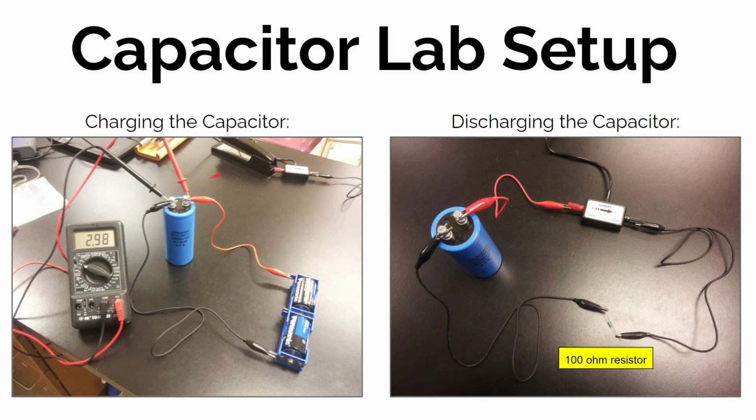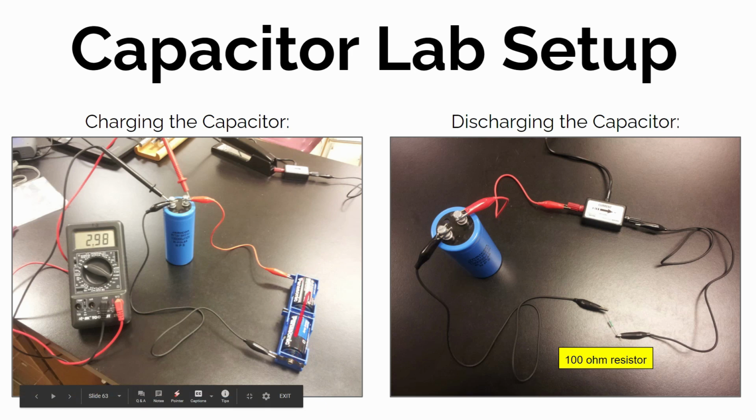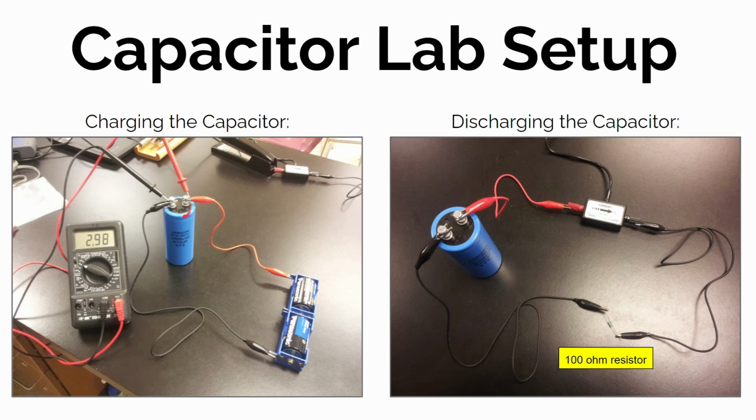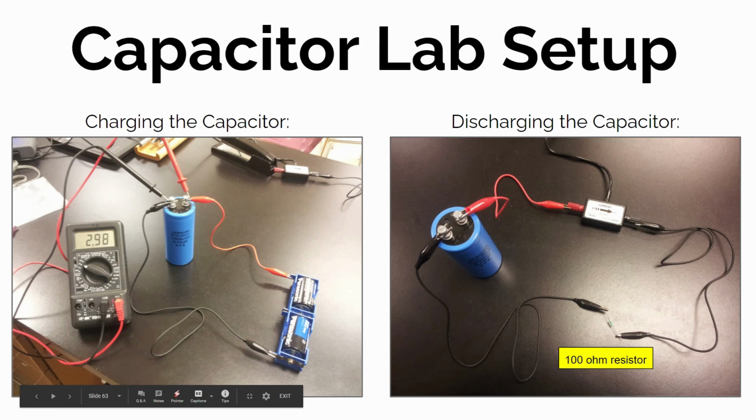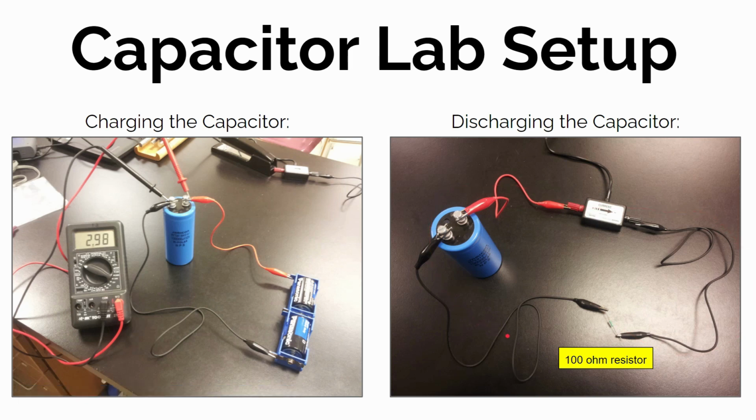And one last reminder, this is how the setup looks. Use different amounts of batteries connected together in a row to force there to be a different potential difference across these two plates. You're charging the capacitor here, then you disconnect the batteries and basically make a conductive path from the negative side to the positive side with our current meter inside of there and our little device to kind of slow down the flow. This is where you're going to get your current versus time graph so we can figure out the amount of charge that was actually stored in that capacitor.